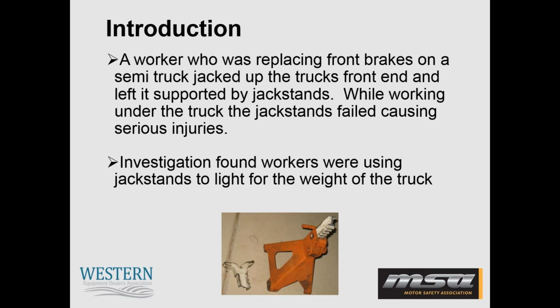I'm going to kick it off with a completed case study courtesy of WorkSafe British Columbia. This will be sent out to all the attendees today. A worker was replacing front brakes on a semi-truck, and the truck was jacked up and supported by a pair of jack stands, which is correct. However, while working under the truck, the jack stands failed, causing serious injuries. As a result of the investigation, it was found that workers were using jack stands that were too light for the weight of the truck. So this is a good reminder to know the weight of the equipment you're lifting and use the correct equipment.